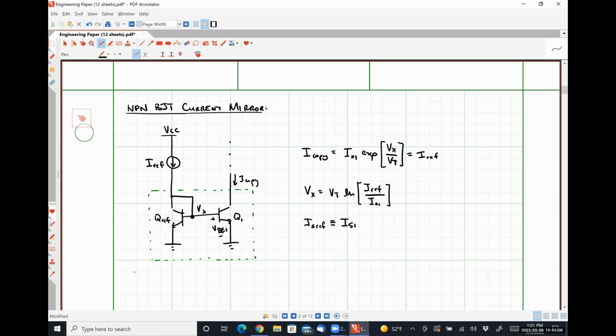If the circuit is at a steady state condition, then the temperature at which the circuit operates will be at a steady state condition as well due to ohmic losses and all that kind of stuff. So it's really temperature changes due to environmental changes that we're talking about. But you are absolutely right that there is going to be some inherent temperature instability while the device comes up to its thermal equilibrium. That's not really what we're concerned about here.